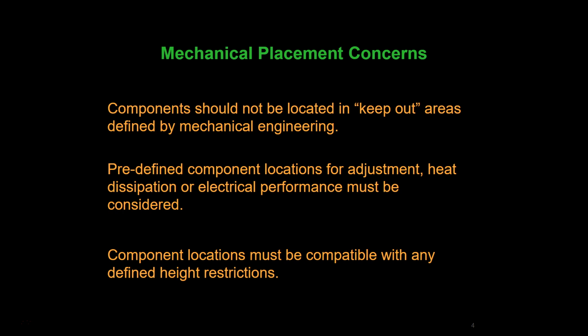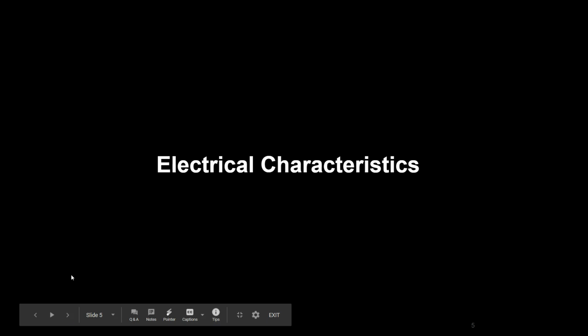So when you design the PCB, before you place a component, you need to make sure exactly where your mounting holes and edge connectors should go, and what kind of mechanical enclosure you need to fit on your board. Understanding these variables will affect both the size and the shape of your board. Moving on to the next slide.